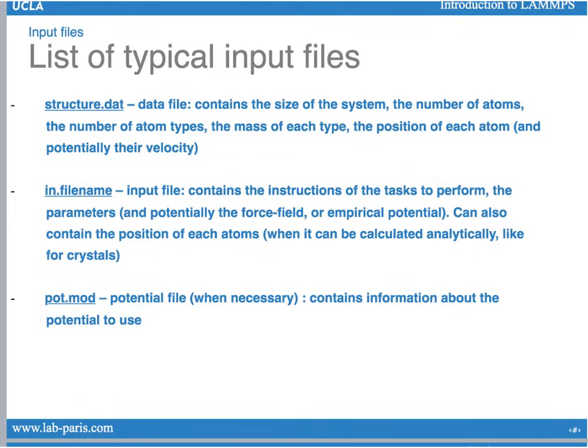And you will also, in this file, put the information about what you want LAMMPS to give you back. Do you want LAMMPS to calculate the energy as a function of time, the pressure as a function of time? What are all the information that you want LAMMPS to calculate for you based on the simulation? All those information needs to be specified in the input file.